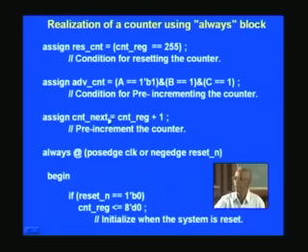And what we need to do is, we just have to increment the counter register, that is the output of the counter which we have already seen, just increment by 1. Note that there is no need for 1 stroke B and so on. It can be a plain decimal number as such, and so the incremented value is assigned as the next value for the counter. Only this is a pre-increment thing. Actually it increments beforehand, and the incremented value will be assigned or not assigned depending upon the condition inside the always block.